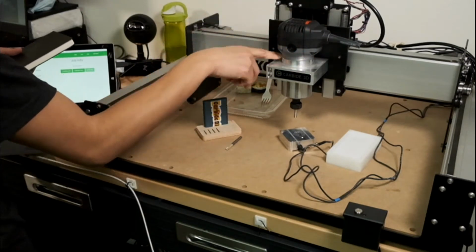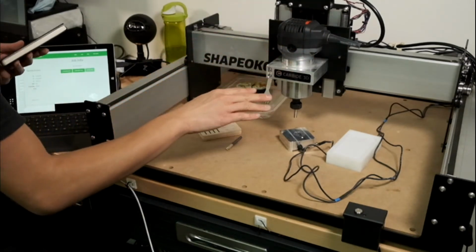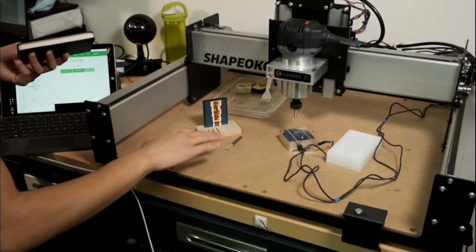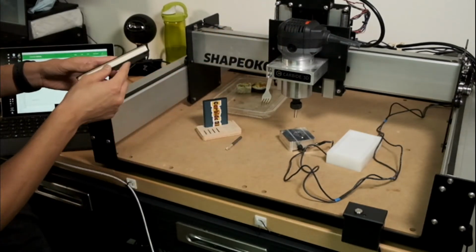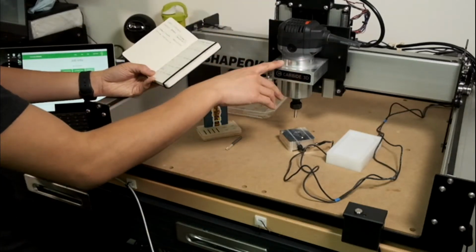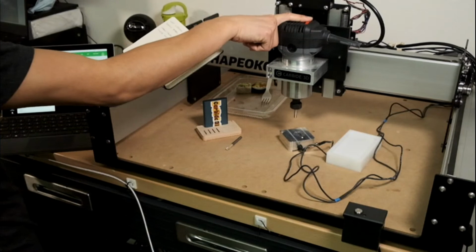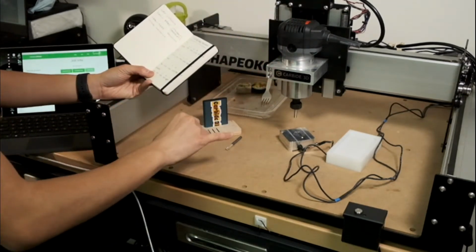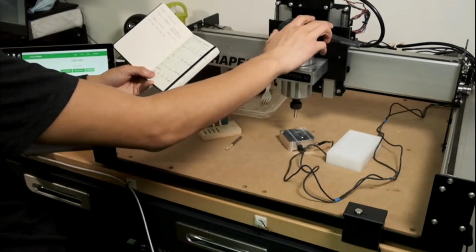But at the top end, this maxes out at around 31,000-ish RPM. At the low end, at 1, it's about 10,000, 11,000, give or take about 10%. So I figured out that, at least on the routers I have, 1 is about 11,000, 2 is about 13,000, 3 is about 15,000, and it's in increments of roughly 5,000 all the way up to 6.